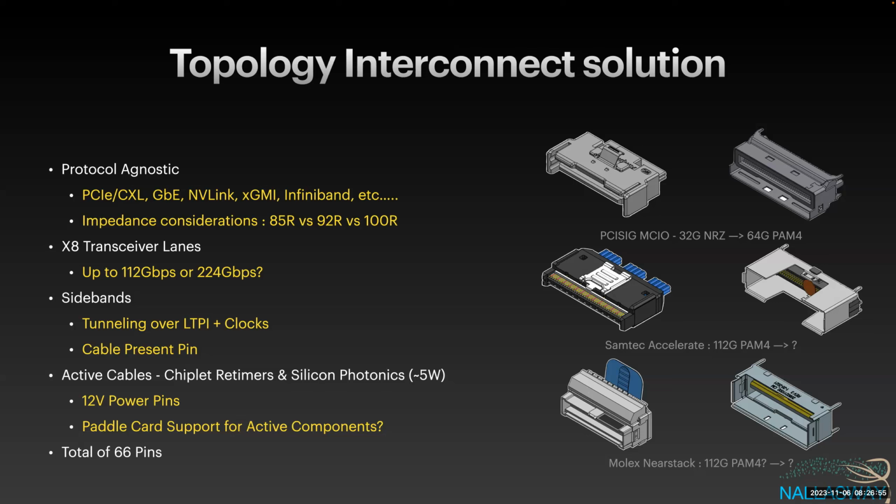So therefore, we have this horrible clash of impedance issues that you guys in the connector world have known about forever. PCI went down the route of 85 ohms, away from where Ethernet was at 100. We split the difference with connectors being 92, but I'm not sure that really helps signal integrity as we traverse these higher speeds.